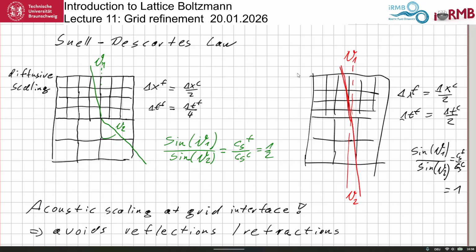So if there's a small vortex that has this pressure minimum, and it is now trying to cross the interface, so that it exists or does not exist to the full extent on the other side, then the pressure balance is no longer valid.